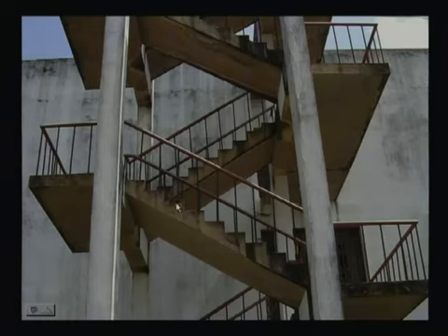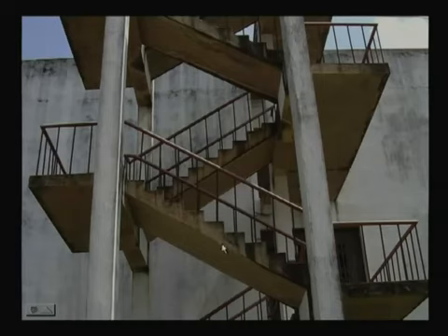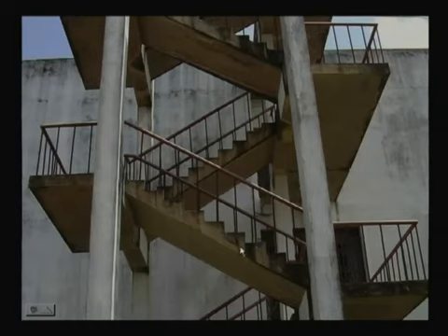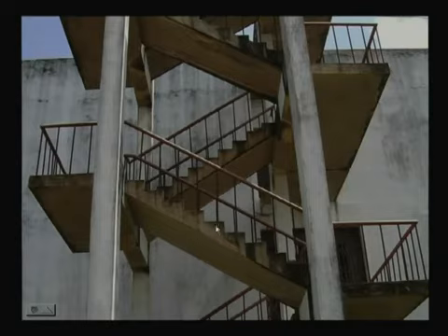What I can say here is there is one step here. You can see all the steps. So you have to consider the dead load of the steps also, the weight of the steps. And there is what is called the waist slab. So how to design this one? In the first one we treated the steps as one after another, but here we are assuming these steps are supported by this slab. That means I can design that slab.